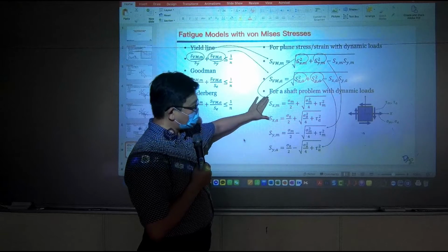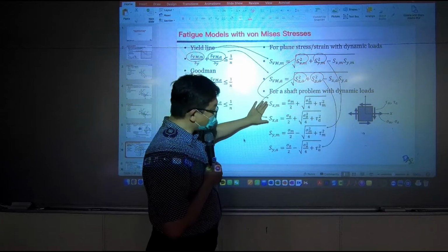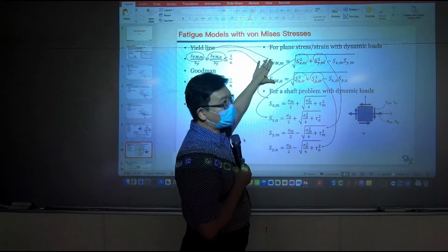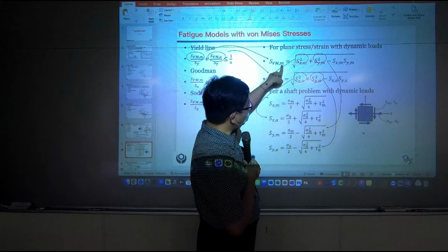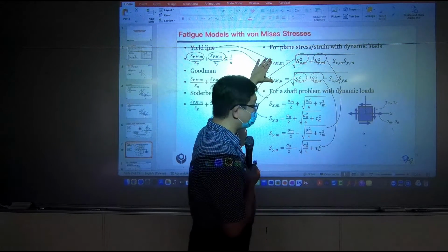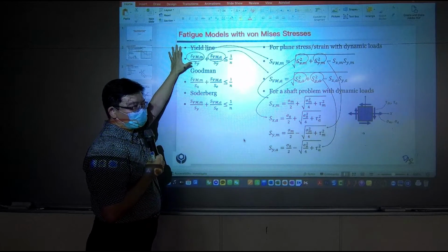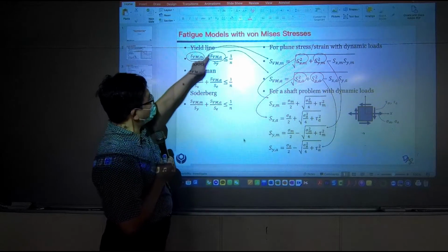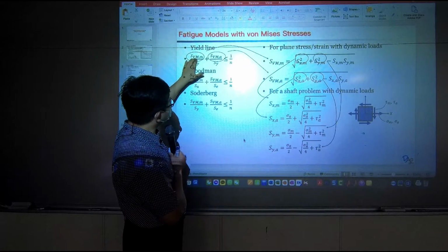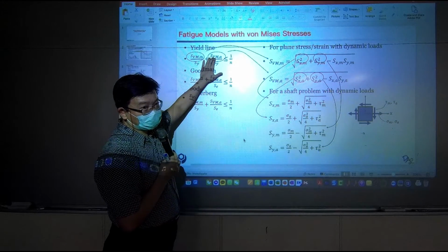With those mean and amplitude values, you can plug into your von Mises equation. You can then get the mean and amplitude of von Mises stress. Then you plug into your fatigue model the mean of your von Mises stress and the amplitude of your von Mises stress.